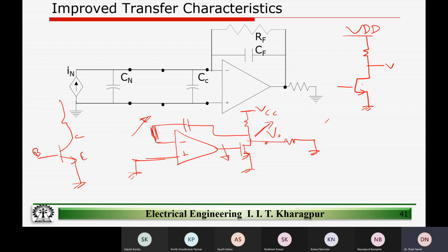So what happens, Ayush, is in many configurations, actually it is done, by the way. And I've worked in such designs where the body, right? So it's a 4-terminal device, right? And it's an NMOS. So the body, if I'm representing the body like having another terminal here, in many places you will see the body is not grounded. Even if the amplifier configuration is like this, right? The body is not grounded. It can be connected to some other voltage.